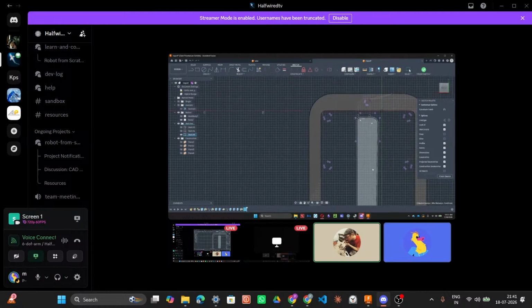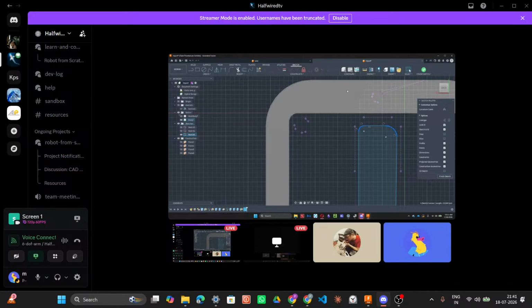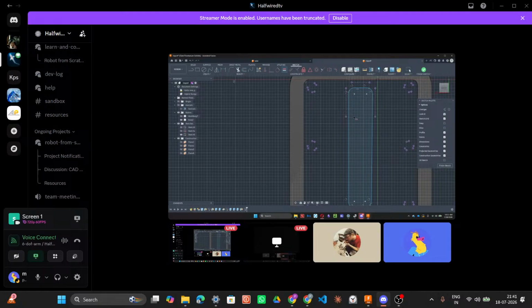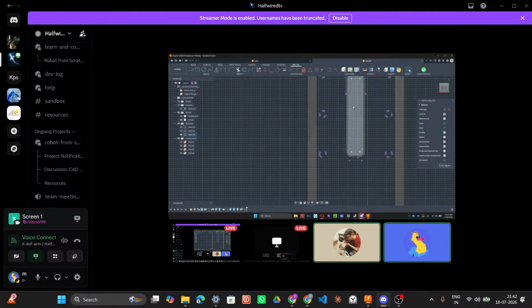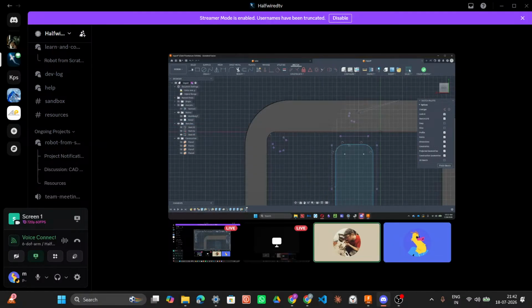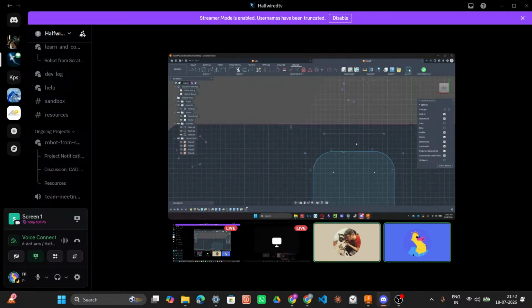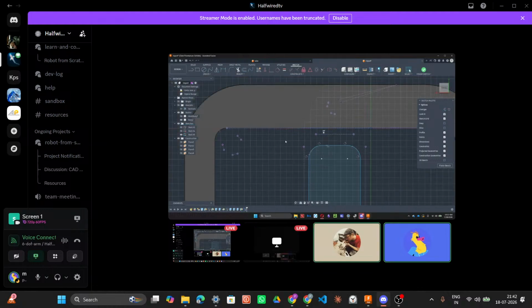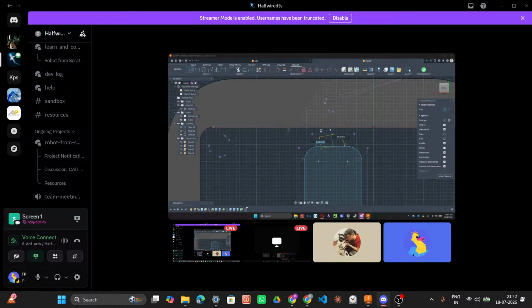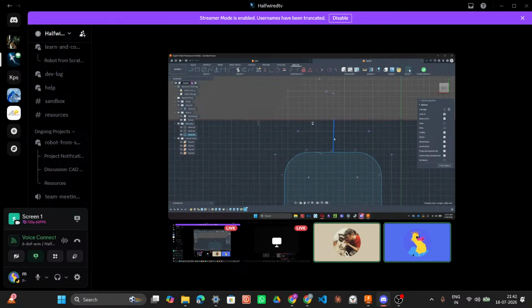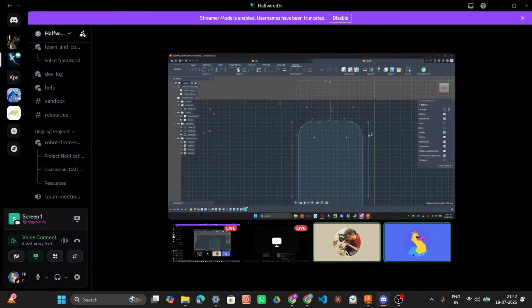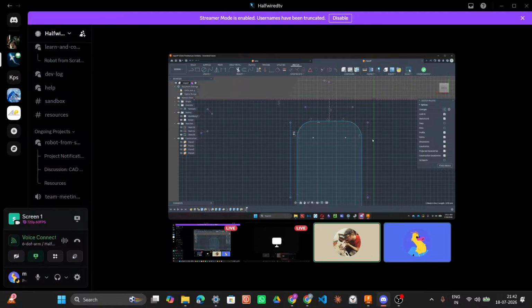Okay. And then I was going to say all of these are equal. This is equal. This is equal. And then I'm going to say the midpoint of this. Oh, I get my original line from my actual shape projected in. So I can say that should be centered, instead of actually using these or doing any constraints off of those.